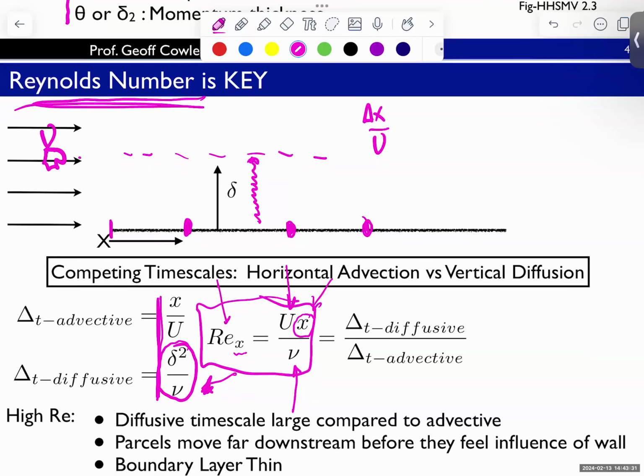So we're defining this Reynolds number, and what we'll see in the formula is when we crank up the Reynolds number, and you can think of it as increasing U, let's keep x at a fixed location. Let's talk about, say, this one. If we draw a boundary layer at a given Reynolds number, let's say it looks like this. And then we say, let's increase the Reynolds number by increasing the flow speed. We'll double the flow, something like this. So this is going to double the Reynolds number.